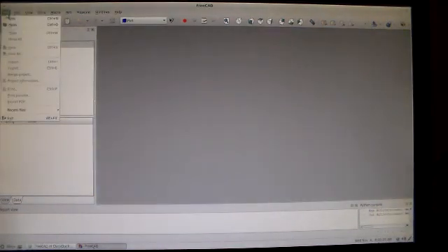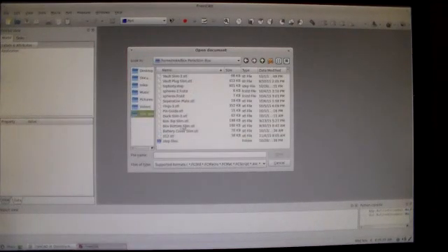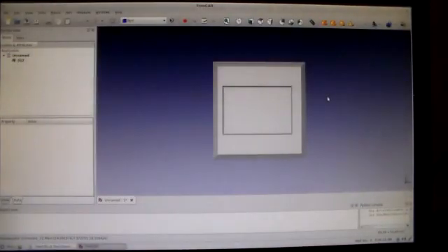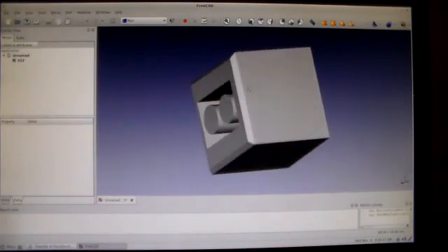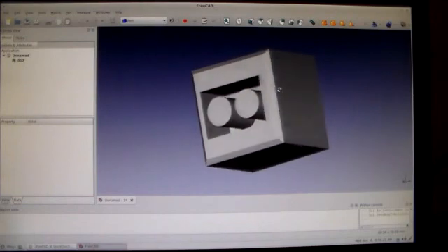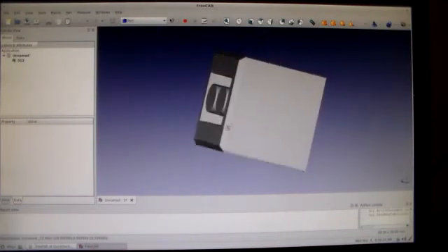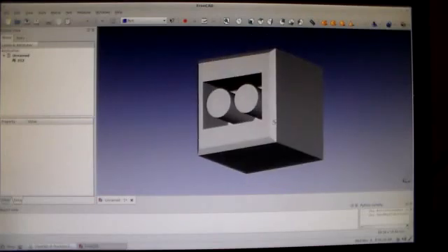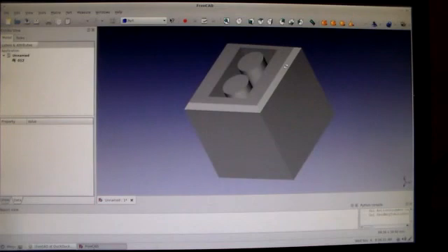Normally you probably want to save it, but I think I put it in here. 012 STL. Okay, now you can see this is an STL file now. The appearance of it is slightly different. But this part you can put into your 3D printer, and of course you want to orientate your parts in a manner that's appropriate for your 3D print job.